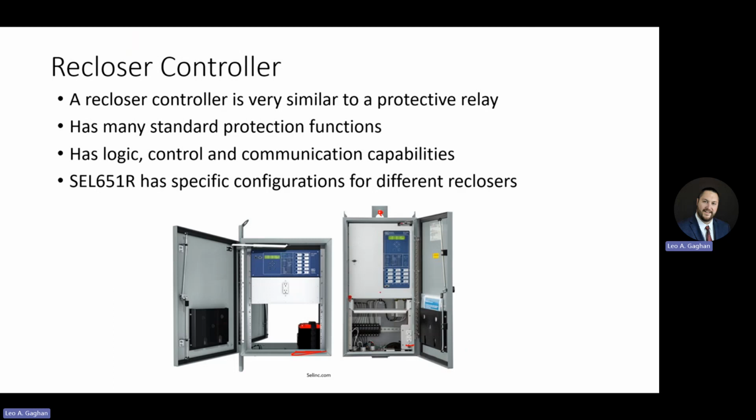But the recloser controller itself is this blue box, very similar to a lot of our other blue boxes, kind of like we've seen in the lab, right? The SEL 451s, 421s. Very, very similar as far as operation. These particular ones, the 651Rs, you program with AcSELerator, just like a 451 or 421.